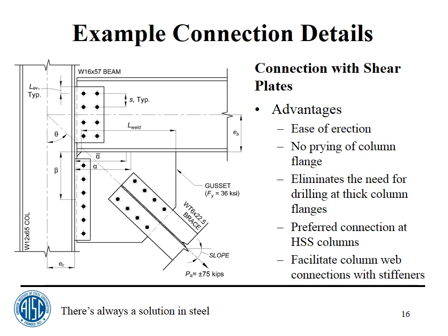And it's easy to erect. It's very, very simple to erect a bracing connection with shear plates, with the shear tab kind of plate, because the connection, the beam with the gussets and everything attached, can be brought in laterally. There's no issue of sliding it down the column if it's going to a column web. There's no issue of cramming it between the column flanges.